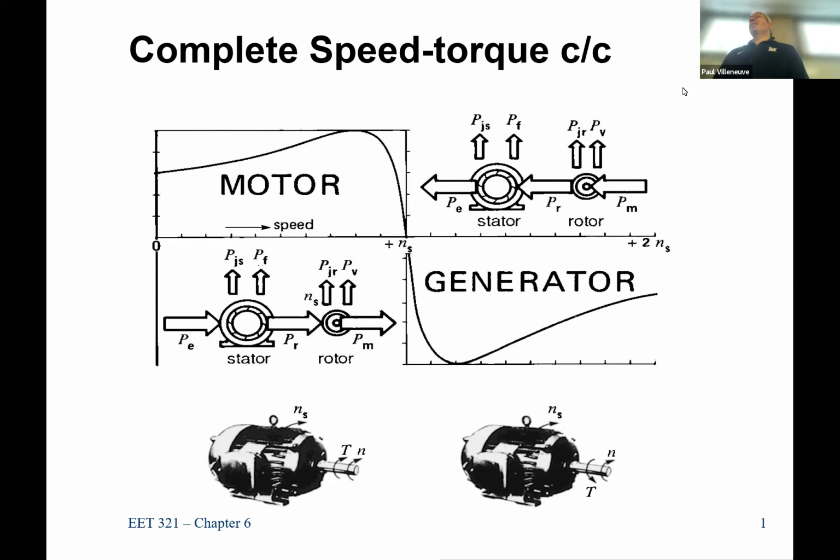So as we talked about in class a number of times, any AC machine can operate as a motor or a generator. It just depends on the application and torque. In the synchronous motor, it has to run at synchronous speed. So whatever we're driving it at, that's whatever output frequency it's going to be. Over here, will you get an output frequency?